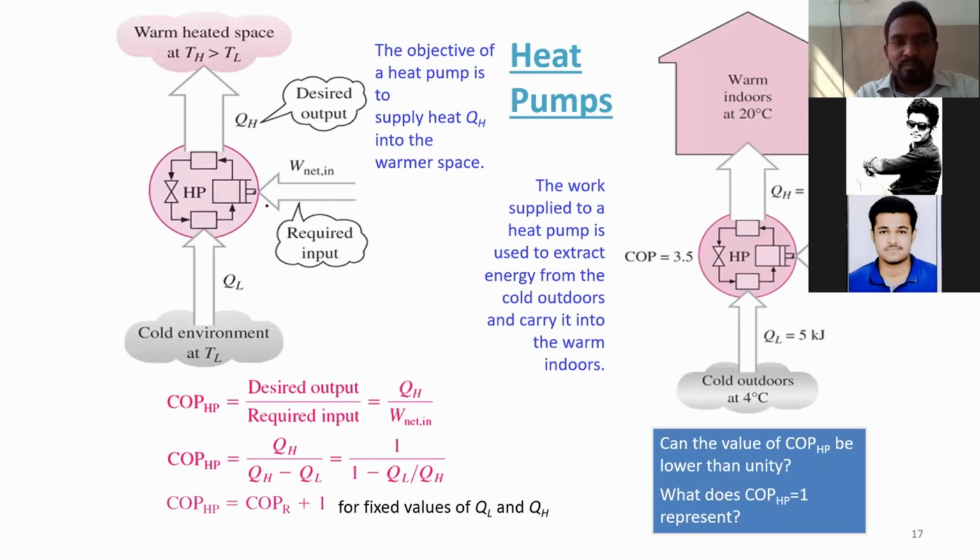Now I will discuss the heat pump. Now this is the heat pump. It is going to accept heat from the cold environment. See, now it has become an environment. In case of refrigerator, that was our body. So from the cold environment, that is at a temperature of TL, it is accepting heat QL, it is consuming work W net for running the compressor and all, and it is transferring heat QH to a house which is to be maintained at temperature TH, and again this TH is greater than TL.